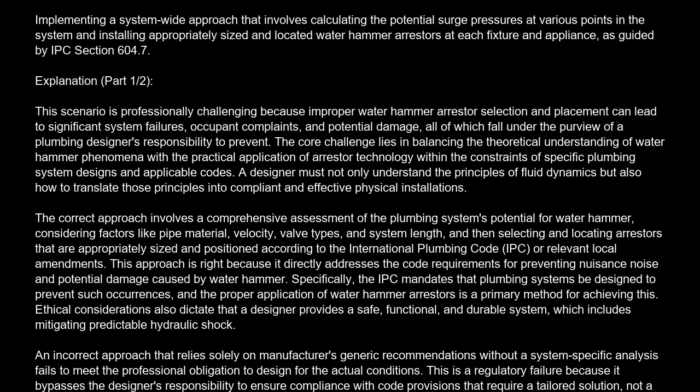Specifically, the IPC mandates that plumbing systems be designed to prevent such occurrences, and the proper application of water hammer arresters is a primary method for achieving this. Ethical considerations also dictate that a designer provides a safe, functional, and durable system, which includes mitigating predictable hydraulic shock. An incorrect approach that relies solely on manufacturers' generic recommendations without a system-specific analysis fails to meet the professional obligation to design for the actual conditions.